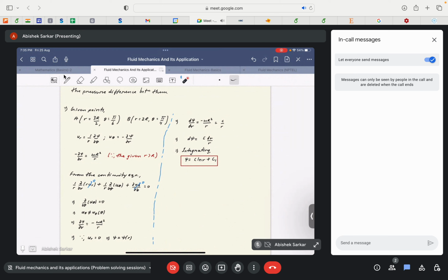Since it is already given that the flow is incompressible, steady and 2D, and essentially now 1D because there is only one velocity component, the definition of stream function still holds. So we can now apply the stream function to find the equation of the streamlines, so that we can check whether these 2 points lie on the same streamline or not.